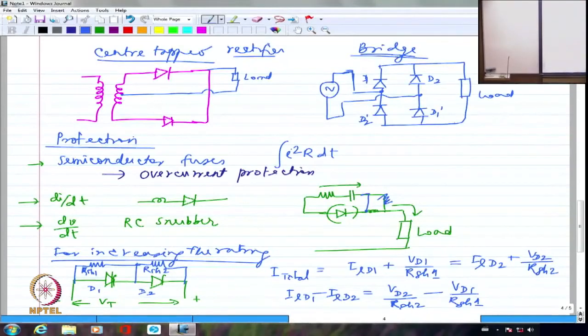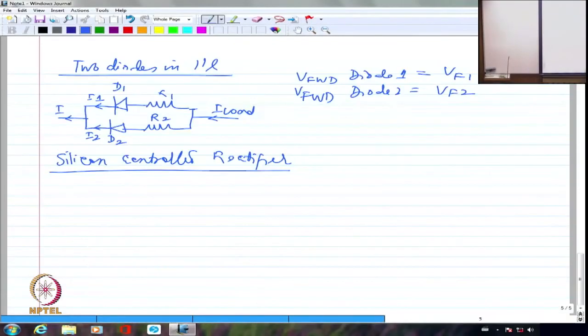Doesn't make sense. Right? So as far as silicon controlled rectifier or SCR is concerned, this is basically a 4-layer device. We normally say a diode is a 2-layer device, P and N. Transistor is a 3-layer device, PNP, NPN. Whereas this is a 4-layer device. So I'm going to have PN, PN. This is how it is going to be.